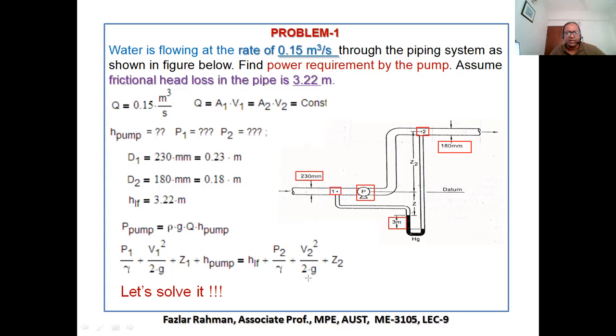If you make a line right through over here, then from point 2 coming right over here, you get the pressure over here. Pressure, say at this point, will be equal to P2 plus this much height coming down. Similarly, on this side, you get P1 plus the height coming down, including this much height of the water and this much height of the manometric fluid. That is given.